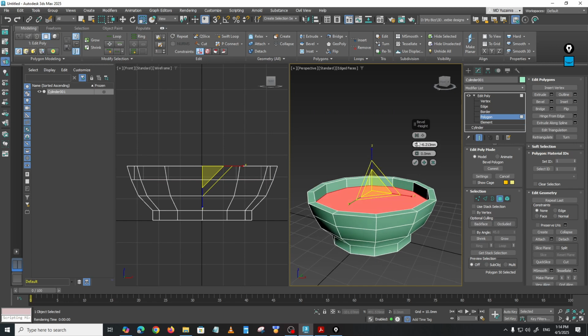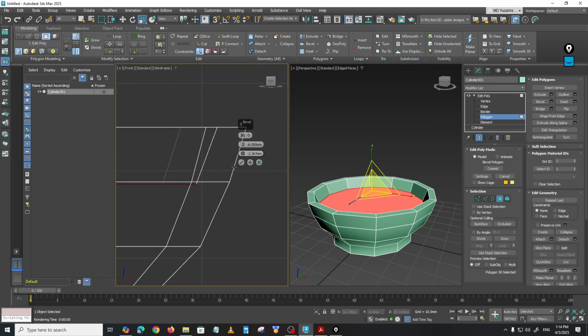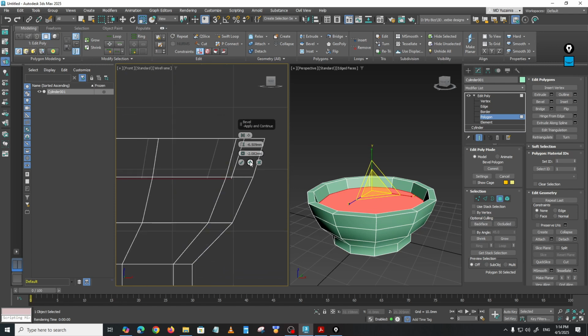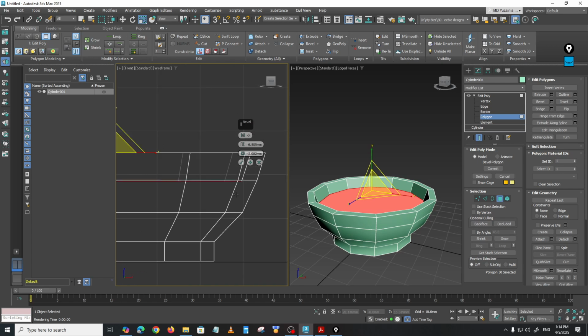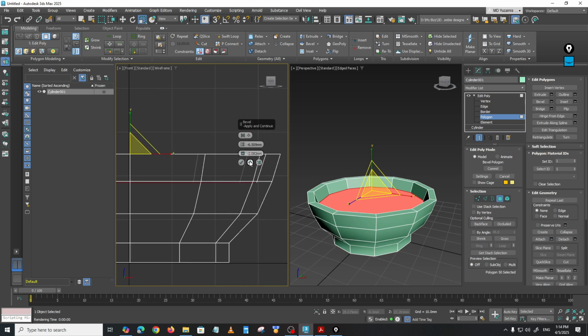Okay, I'm going to stop from here, and then I'm going to adjust the width to go smaller a little bit, so that it follows this angle here. You can see first it's straight and now it's inside. See, it's going inwards. This is the thickness. Alright, so once we've done that, we hit plus to continue beveling again. I still want to continue, hit the plus.